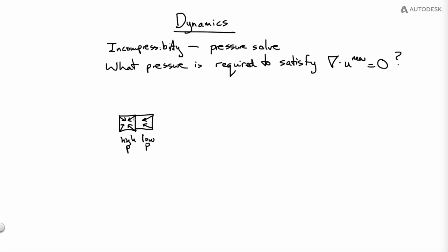So the high pressure will force the fluid to not squeeze into this grid cell, but instead sort of balance between the two. Of course, the thing is, it's all globally coupled. So if we put a high pressure here to fix this, then it might push into the neighboring grid cells over here, and we might have a divergence problem in there if now suddenly the fluid is pushing into there, and then if we fix that with a pressure there, it can cascade over. So really this is kind of a globally connected problem.